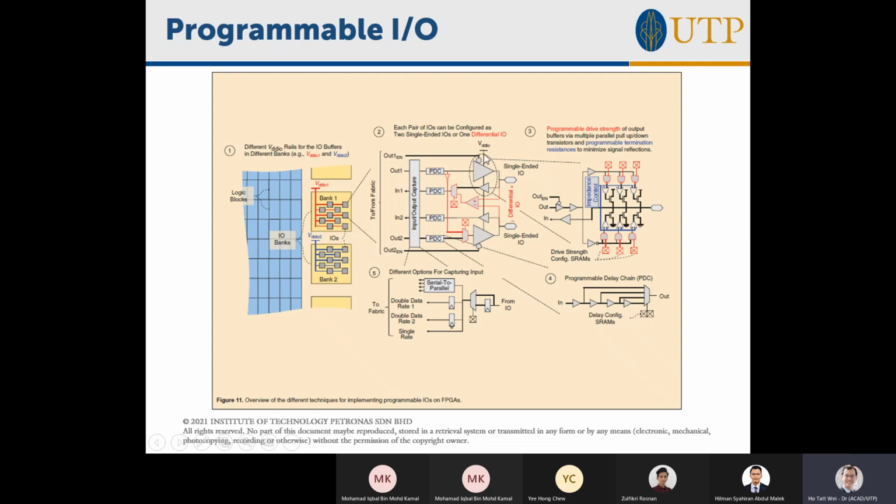And you can set not just the type of logic family and the voltage. You can also set what we call the drive strength. That is how much current I can push out of this pin, or how much current I can sink into that pin. This is also very important in circuits. Let's say you're going for high-speed or low-energy circuits, you might go for a weak drive strength. But if you need to drive very long wires on the PCB, the electronics board, you have to change your drive strength. So you can specify whether your pin is going for a few tens of milliamps, or 1 milliamp, or a few microamps. What it's doing is connecting in parallel one or more current sources.